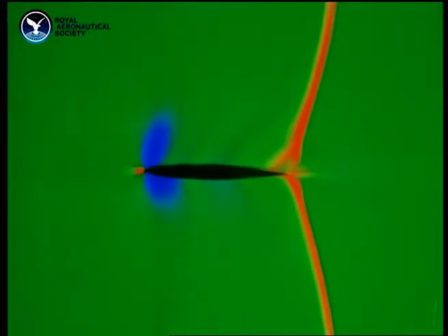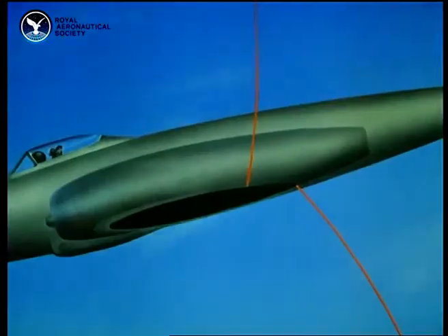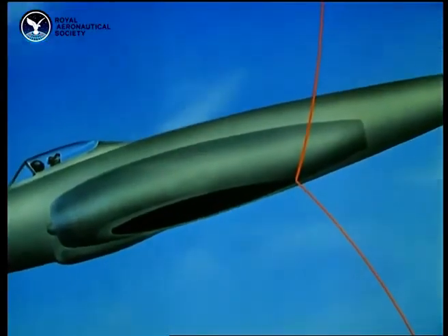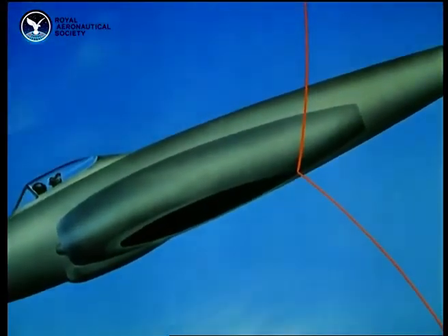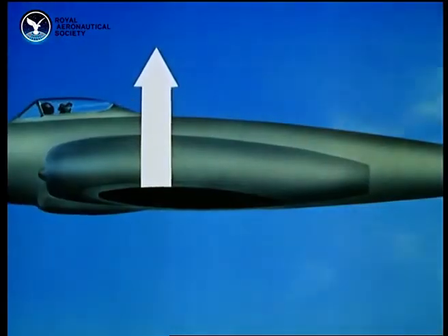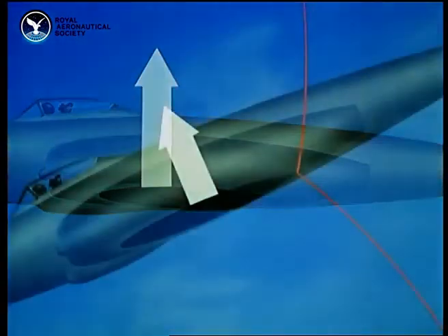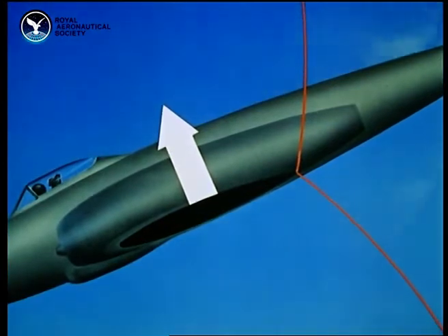Finally, the top shock also moves to the trailing edge, making the aircraft go more nose down again. Most aircraft don't do all of these things, but the center of lift always shifts towards the rear when passing through the transonic range. So all aircraft suffer a final nose-down trim change.